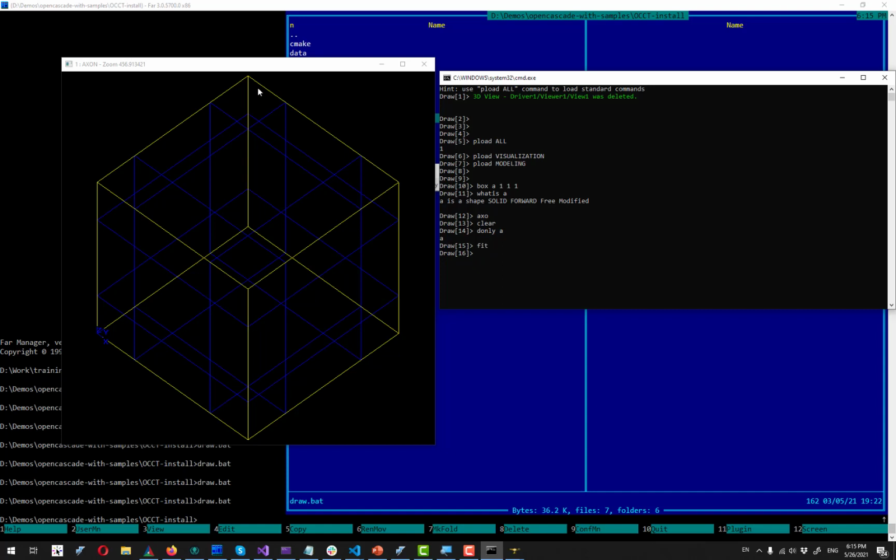So the color codes here in this viewer are not random. Yellow color means that the corresponding edge is shared. It means that this straight curve segment here is shared by two faces. And you also see these blue lines over here. These are just isoparametric lines of the corresponding host surfaces for my faces. I have all my faces planar.